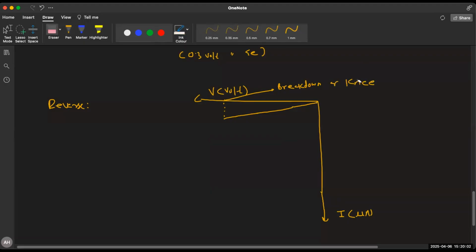Not breakdown voltage, or zener voltage. Once your applied voltage is equal to breakdown voltage or zener voltage, current increases almost linearly. Your current increases but there is no change in voltage. What happens here is V is equal to IR. When your applied voltage is equal to breakdown voltage, then silicon bonds break. You get new charge carriers which decrease the resistance, but you are increasing the current. The product will remain constant.